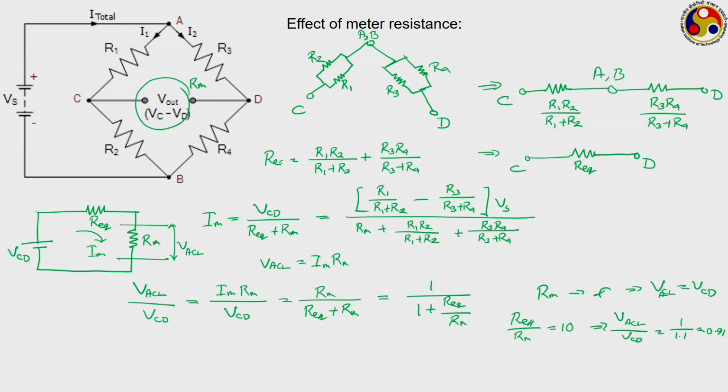So, this is the way we can analyze any Wheatstone bridge circuit. This kind of analysis for the Wheatstone bridge circuit will repeatedly come back, particularly the sensitivity-related issue, which we shall be discussing repeatedly in the case of strain gauges and other devices.